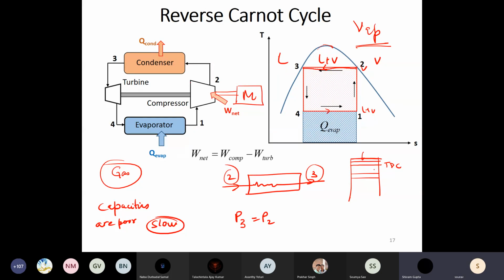And that is how you can attain very high pressure ratios. Now, this is assuming that you have a fluid which is compressible. Now, think that you have a large amount of water present in this, and still your reciprocating compressor will try to compress it by this much. It will try to compress that volume of water present in the piston cylinder assembly to this volume.